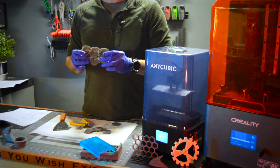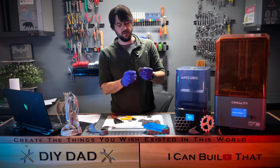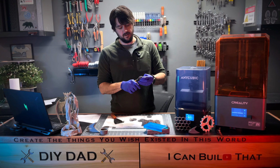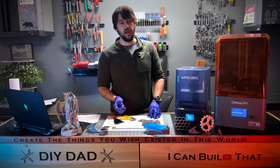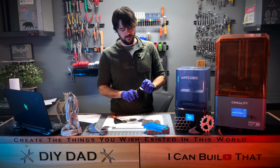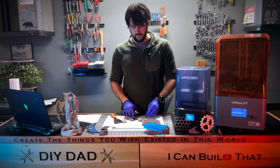With that, you have the remainder of your supports, which can be thrown away in the trash. At this point, you may have small bits of supports that remain on your print. That's okay. We'll still take our clippers and clip those remaining little bits off. It's also perfectly acceptable at this point to use a little bit of sandpaper and rub those down. However, I would recommend putting your 3D prints through your wash and cure process before sanding them, so as to preserve your sandpaper's life. It makes it last longer if you don't get the wet resin inside your sandpaper.